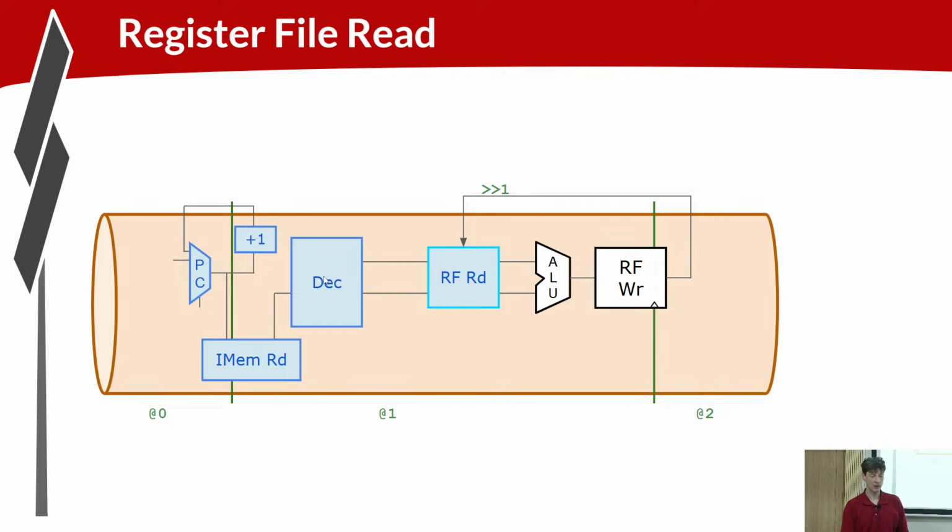Other aspects of decode, for example forming the immediate, are not on the critical path. We don't need the immediate field for most instructions until after we've read the register file. That's one reason the immediate bits are more scattered. We can afford a little bit of delay in that logic to figure out what the immediate bits are.